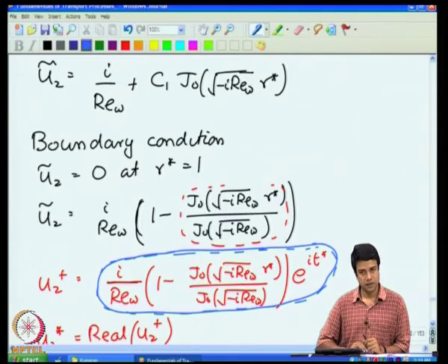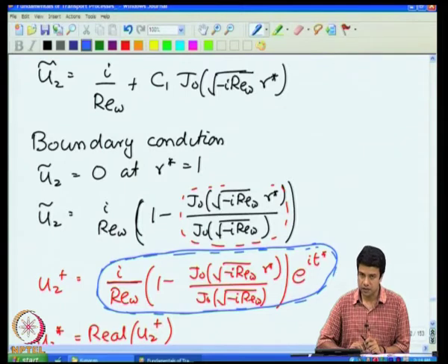However, one can get a better physical understanding by looking at the limits of high and low Reynolds numbers. As I showed you, in the limit of low Reynolds number, the inertial term in the equation can be neglected in comparison to the viscous term. In this particular case, once again there is a balance between the pressure gradient and the viscous term in the momentum equation.